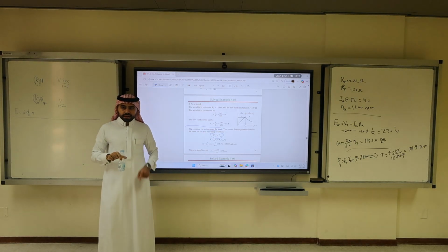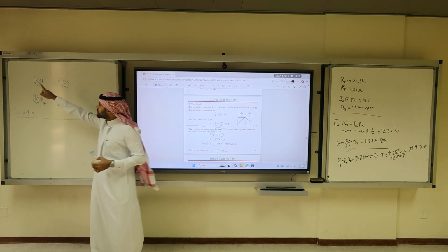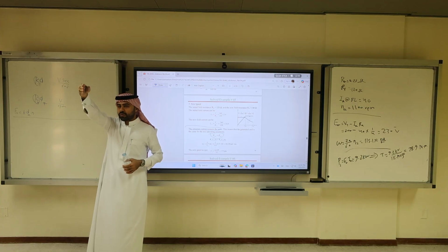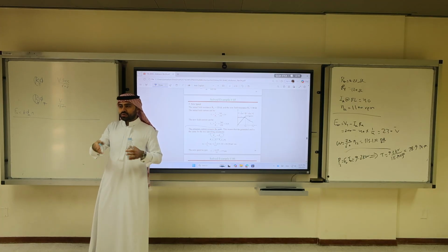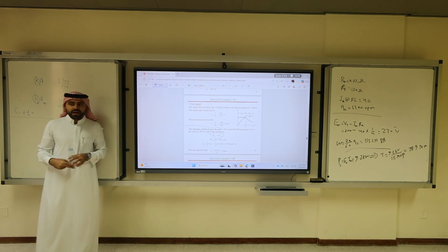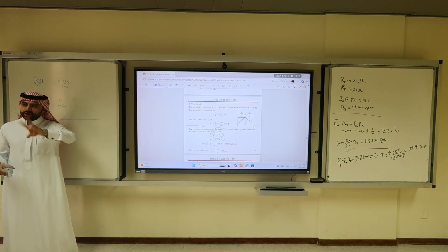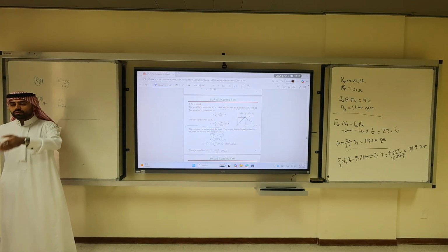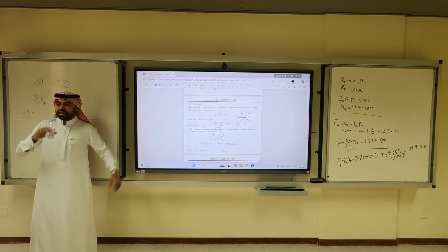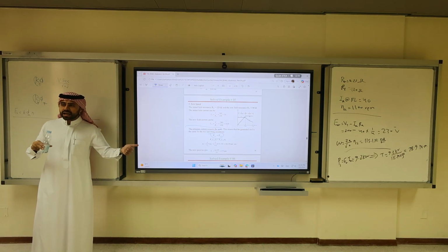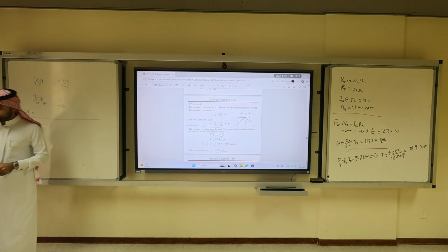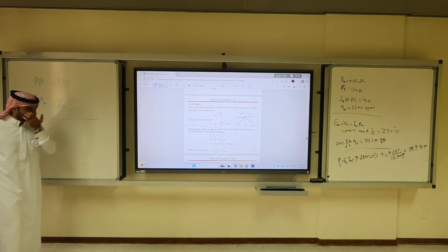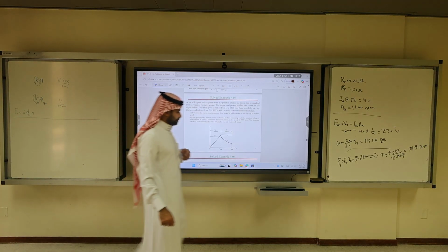Right. If the drawn current is not fixed, you have to use KA times the flux. You have to have a new EA. Because a new EA will be higher, you have to go through other equations, okay? They have to tell you what will happen to the torque or speed, one of them. I cannot give you a problem without telling you what will happen to the torque and the speed if I don't fix the IA. Fixing IA means fixing the power. Clear? So is example 5 clear? Let's do example number 6.